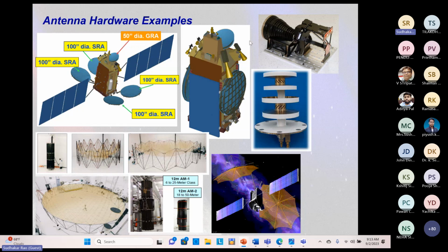When you measure the whole feed assembly, you should get a return loss of more than 22 dB, which is a typical spec. We don't design for 10 dB or 5 dB return loss. You have to design for at least 25 dB return loss. Then, of course, with temperature, it changes a bit, so you can meet a 22 dB return loss requirement.